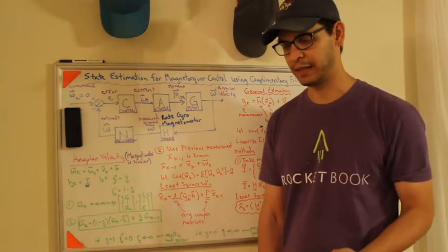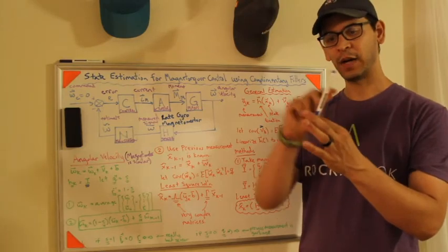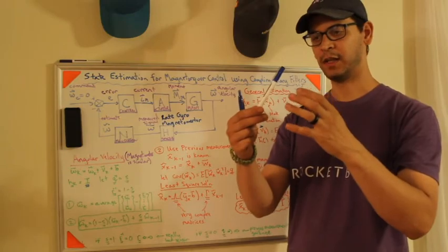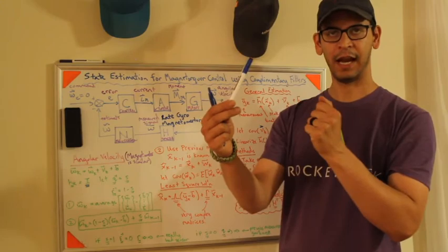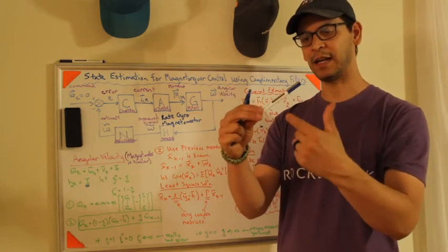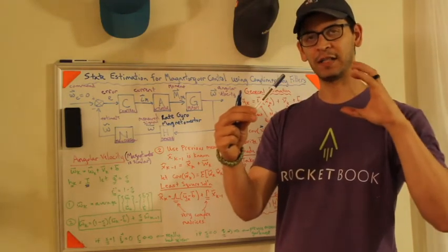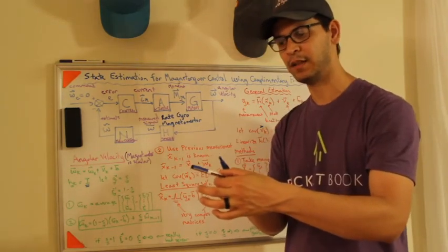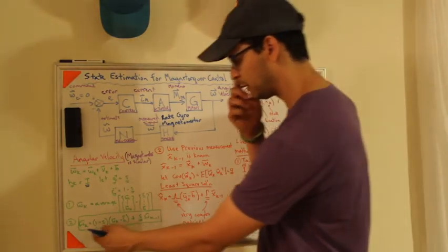The problem with a method like that is, what happens if the spacecraft is tumbling quickly? If this were a perfect system, you could pause physics and take 100 measurements and then average all of the signals. But you can't do that, because in real life, everything takes time. So as you're taking data, the spacecraft is moving. And so you're trying to take these angular velocity measurements while the spacecraft is moving. And unfortunately, that's going to really throw off your data. So the better way is to use this complementary filter.